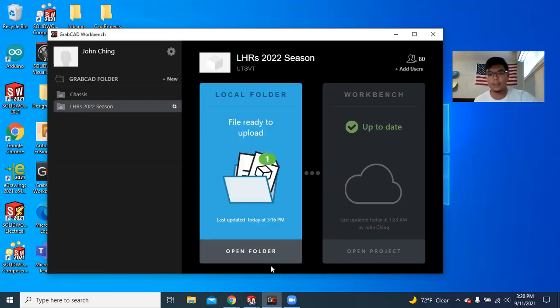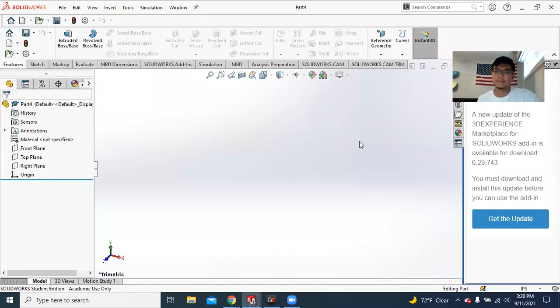Right, so now let's go to SolidWorks. Start a new part. Before we start making the parts, you want to make sure that you have the correct units for your documents. The machine shop and most tools, most of the things we can buy, are in standard units, so we want to work mostly in that.